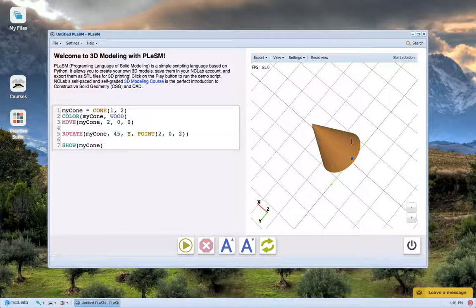And then lastly, remember that to specify an axis of rotation for the rotate command, we need to add a fourth parameter, which will be added with a point on that axis. And then the rotate command will construct a rotational axis parallel to the one specified by the third parameter, but which also passes through the point defined in the fourth parameter. Play around with 3D rotations. They can be hard to understand at first, but they're very powerful once you do understand them.